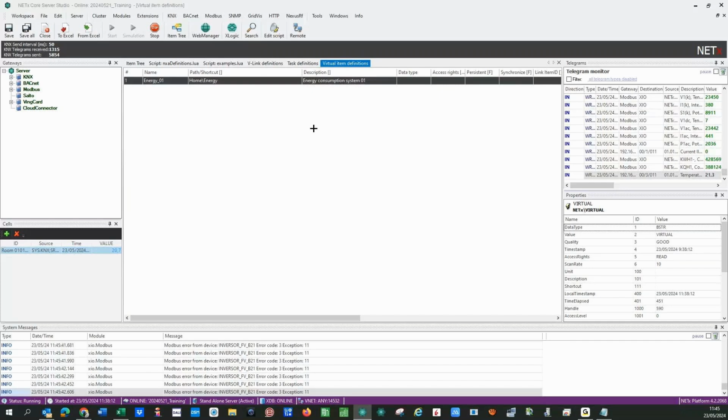Whatever description, and now the item has or needs a data type. This is important to select the right one. If you select integer, you are not doing a good job, because I will multiply by a factor, so it will need decimals. So float, that is real 32 bits, would be good. Maybe double, real 64 bits, is also good, but float is okay.